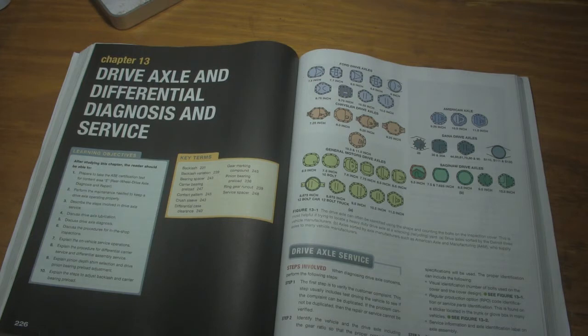bulletins. You might need to hoist the vehicle up in the air and run it in drive in order to identify where a particular noise is coming from. So let's say it's a pinion bearing versus an outboard axle bearing. You might not be able to pick up on the outboard axle bearing specifically. All you might be able to hear from the driver's seat is a noise coming from the back, and having the vehicle up in the air with the wheels engaged and driving while walking around the vehicle, you might be able to then identify where that noise is coming from.